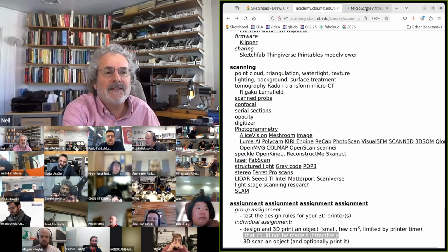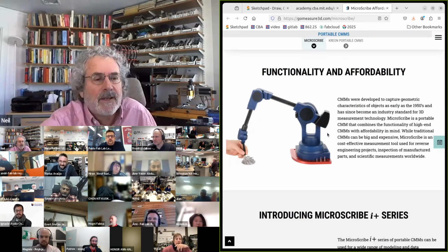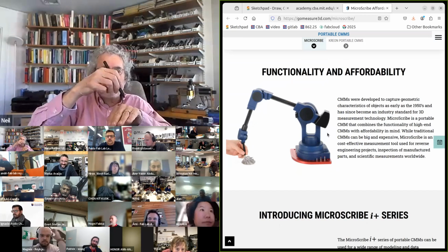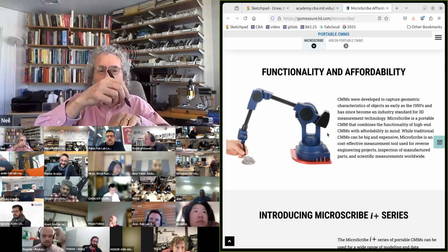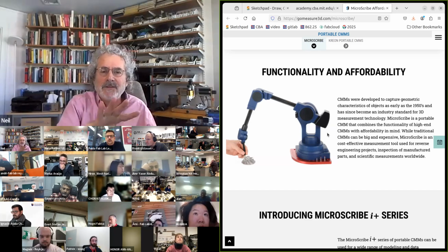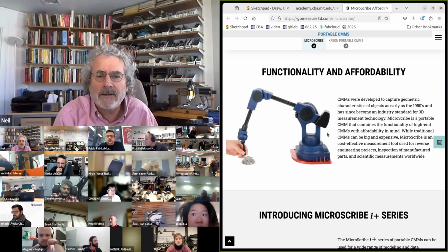This is easily neglected. This is a digitizer arm. It's not automatic. You take an object and you touch points and then you click a foot pedal or a pen. This doesn't scan the whole object. It measures the dimensions that you want.